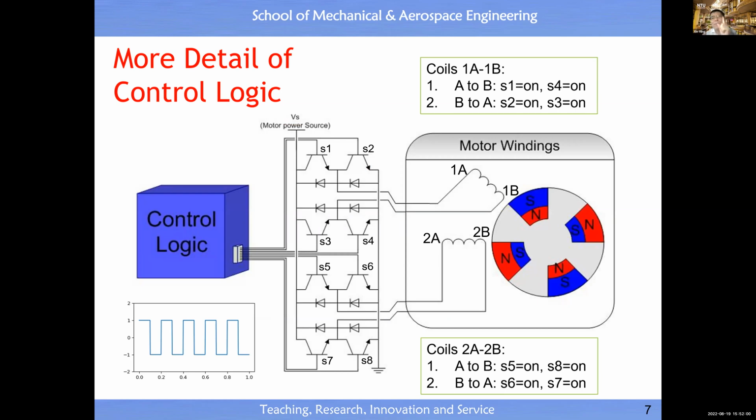And for stepwise motion, remember, okay, we can move for 1 step, then stay there for a certain amount of time, then move another step, stay there for another amount of time. But this can be controlled by the width of the pulse. You see, we have a positive pulse, okay? We can control the width, the timing, okay? This is how long signal 1 will last, okay?